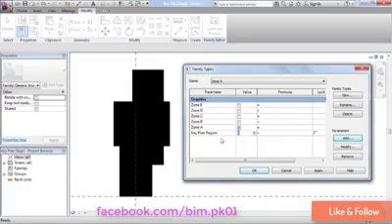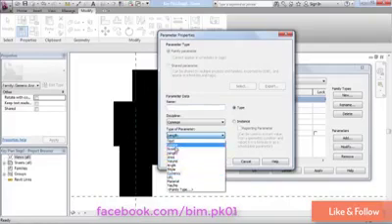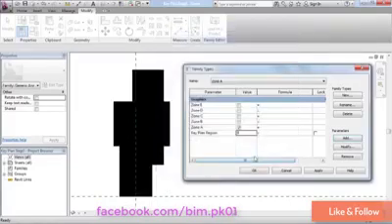Unfortunately, they don't have a character parameter type, so I had to go with integer here and use a number, but that's not the end of the world. Now what I'm going to do is, over here in the zone A formula field, I'm going to write key plan region equals 1. When I enter that, you'll notice that it unchecks the box and it grays out zone A. Now, what did we just do here?